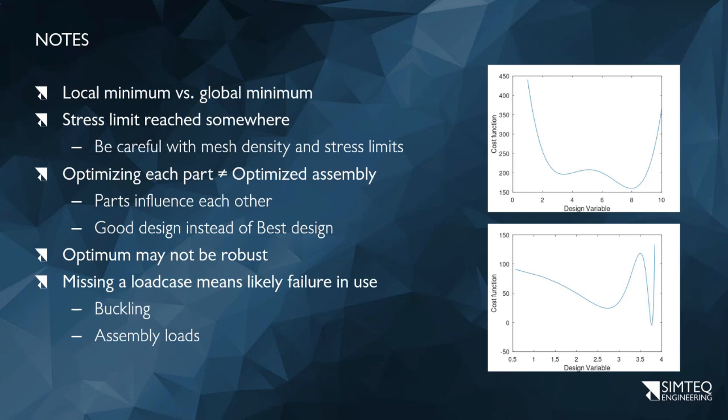In general, structures that aren't optimized tend to be less sensitive to things like buckling and so on, because we've got a couple of plates that are probably a bit thicker than they really need to be. But the closer you get to an optimum, the more important it is to ensure that you've included every possible method of failure. Otherwise, you get a sub-optimum design, because it's minimum mass, but not a valid design. So when you manufacture it, the part will fail before it should, or it fails when it should not have failed at all.